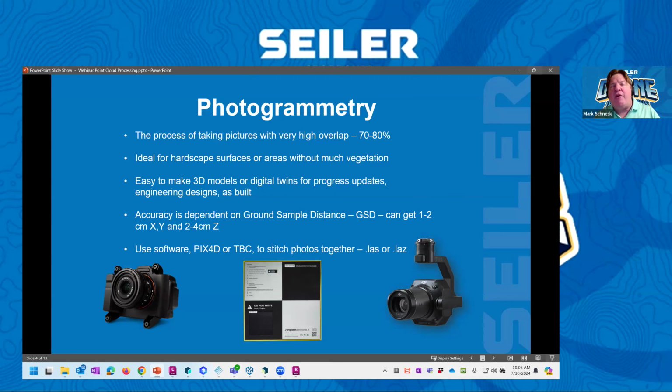So we can get an ortho photo of the entire site meshed together from these. If you're using it for CAD background work or just construction comparison, day 1 to day 2, this allows you to get an accurate orthometric photo of your site for design purposes instead of relying on something that you downloaded, that may be 3 to 5 years old.